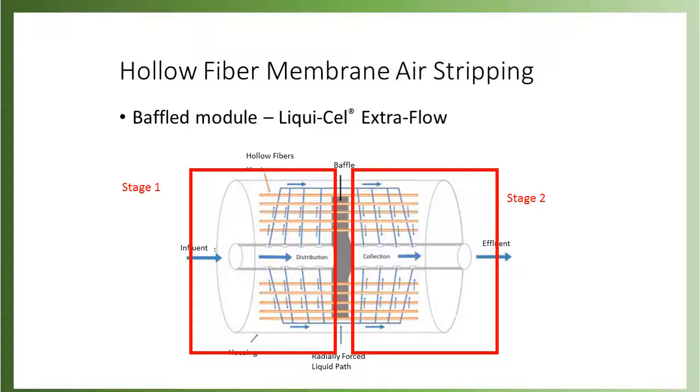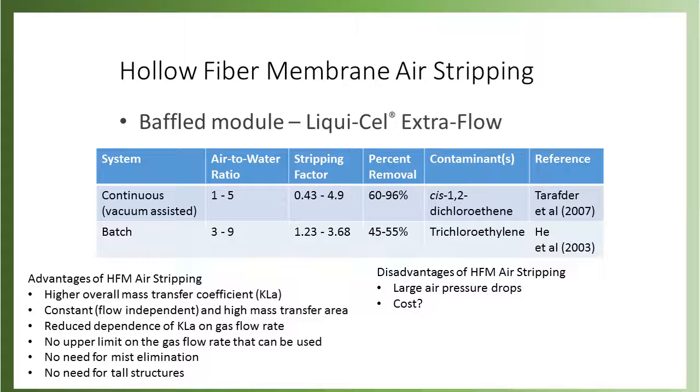Okay? But unfortunately, most of the modeling or most of the predictions were based on models that treated this as an air stripper. And so that was the other problem that we saw. So there were a couple experimental systems that happened with the correct reactor. He had also worked with trichloroethylene. Unfortunately, they didn't run countercurrent. They sort of ran co-current. Kind of doesn't work so well.